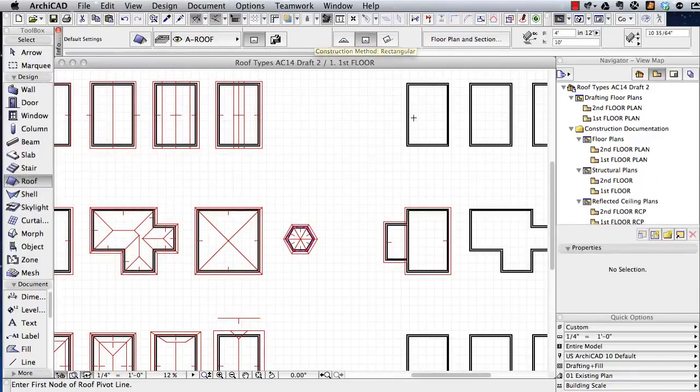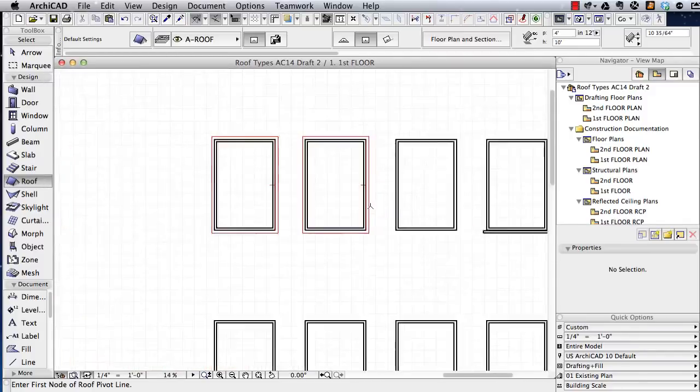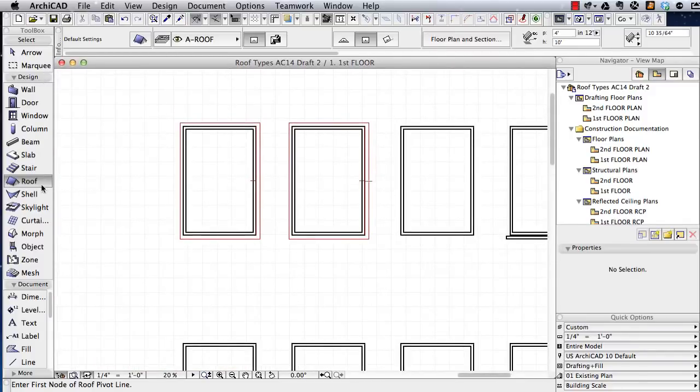So now let's move on to where we're going to use the new styles. And so we'll do a simple open gable roof here, and this one will be the most basic, and it actually shows a couple of enhancements. One is that we're going to be working with a roof system, the MultiPlane Roofs, and the other is that we're going to be working with a gable.